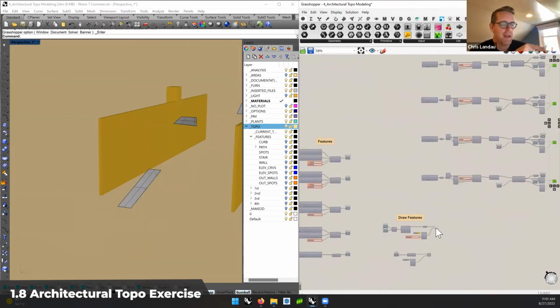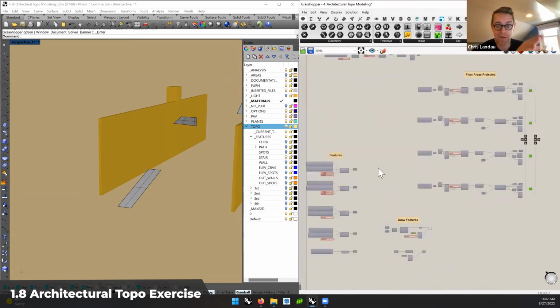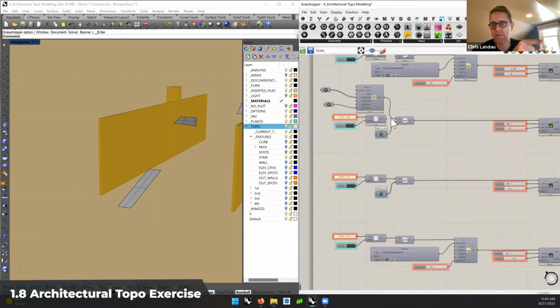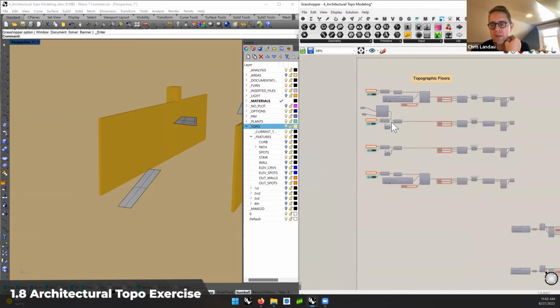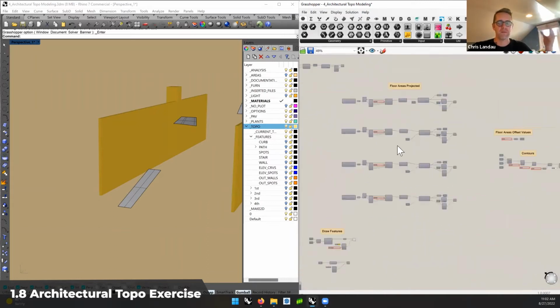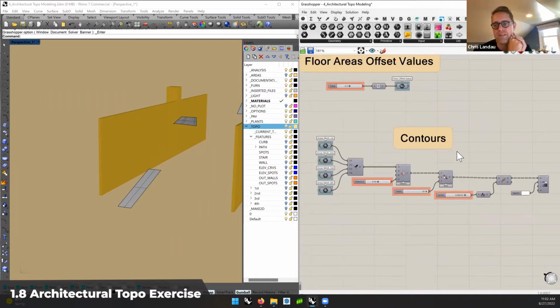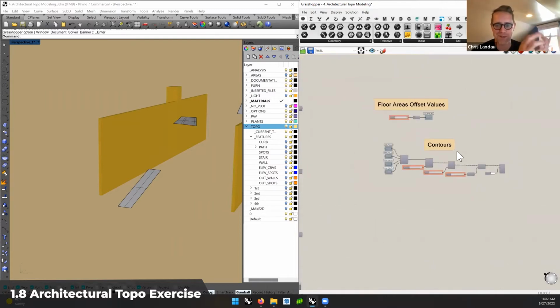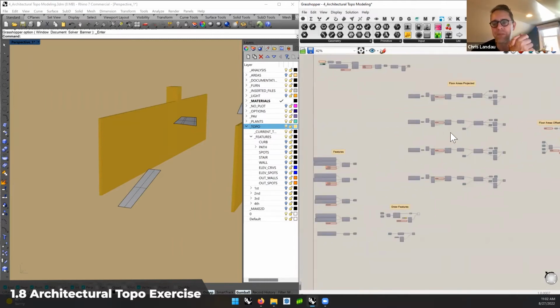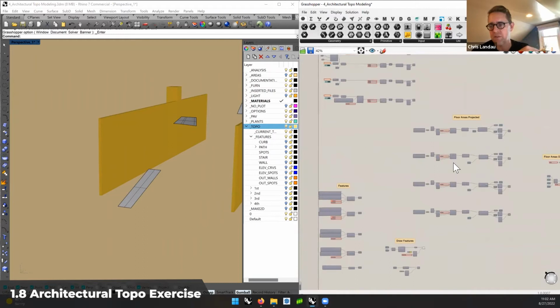There's one concern, which is that when I open the script, there's a Puffer Fish component. Two things. One, you can open it without Puffer Fish. You can just ignore that, and there's a way to fix that, and we can show you that in a minute. I say that because Puffer Fish is, no pun intended, a bloated set of scripts, hundreds of components in a library. If you're designing shoes and stuff, it's a great script, but there may be another solution to do the offset mesh.